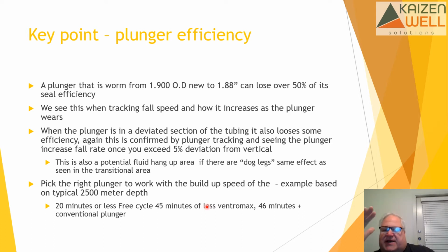There's a whole other subject I have about liquid loading in a horizontal. We know that if you get a fairly significant dog leg, the same things that are happening in a horizontal well as it goes through the transitional are actually happening in those dog legs. So you've got liquid falling down there, even though the well you think is above critical rate, it's really a liquid hang up area. So something to look at.